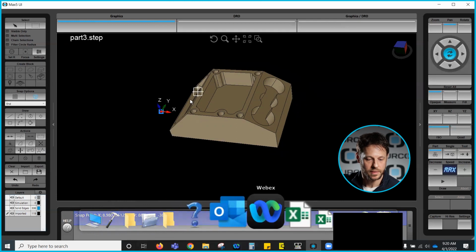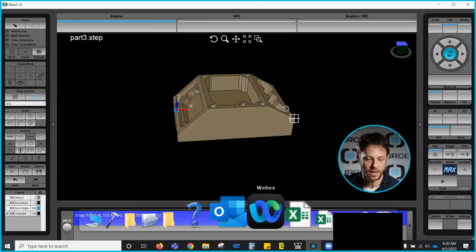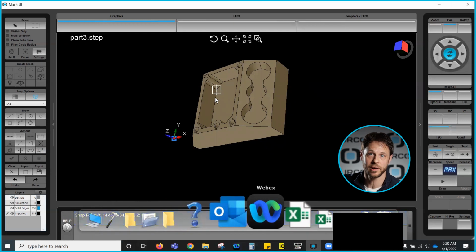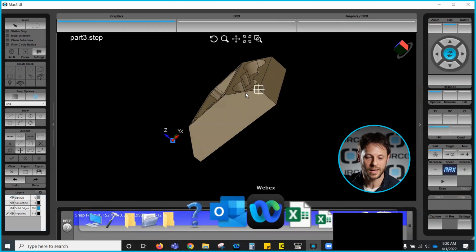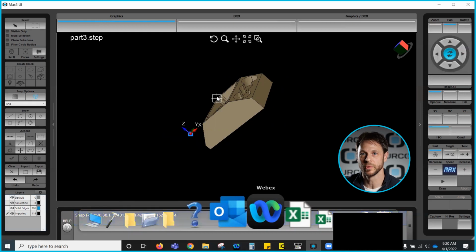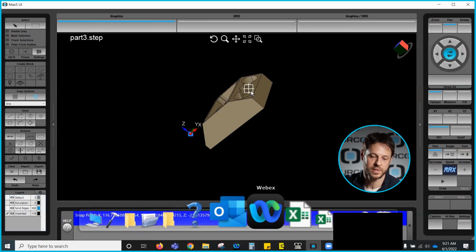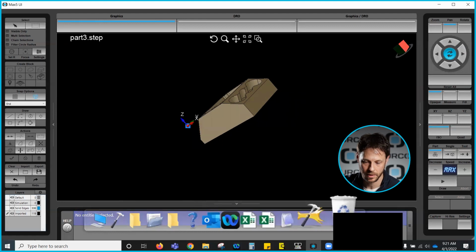So now that we've dealt with moving part zero, which is a relatively easy process, however very important, let's deal with aligning our model to how we are going to have this part fixtured in the machine. In previous videos, we've assumed we were on a 5-axis or multi-axis machine. Now we're going to look at this as if I'm working on a 3-axis machine and I'm going to fixture my part as it needs to be in the machine and come at it, just as you would on a 3-axis machine. Well, in order to do that, we have to change the orientation of our part inside of the software here.